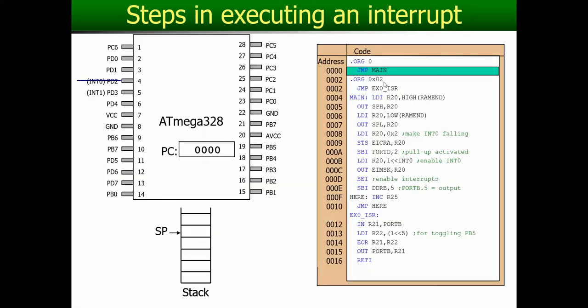This will become 0004 because हमें पता है कि जब external interrupt 1 will occur, it will not be brought to this memory location, it will be brought to 0004, and from there we can then jump to, well, you don't have to change this because this memory address is available as long as it's available. अगर ये external interrupt 0 भी है तो फिर इस ISR को नहीं छेड़ना, फिर आपने दूसरा लिखना है.